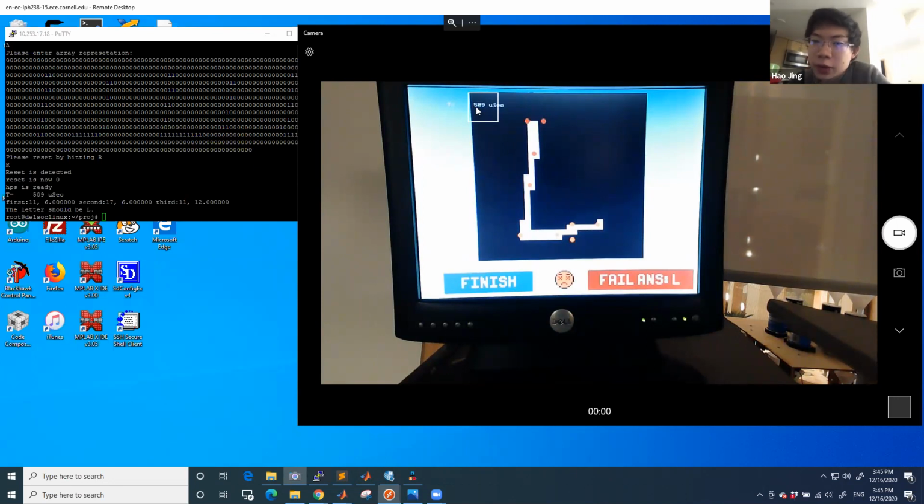So even with this 40 times difference in clock frequency, we still have a speed up. I think a fairer way to compare is to use the number of cycles instead of time. Maybe we can include more of this in our lab report. That's another way we can show our hardware on the FPGA does accelerate this application.